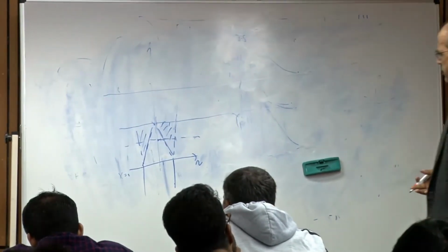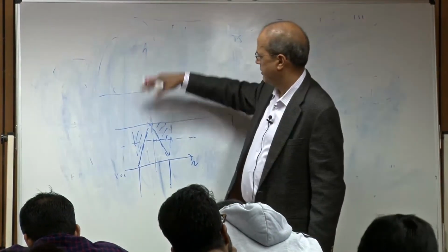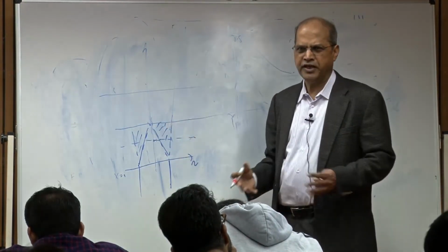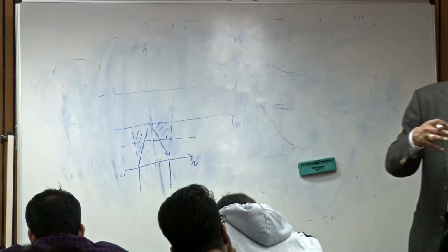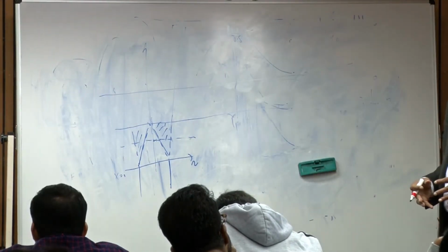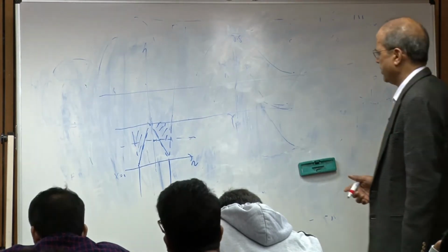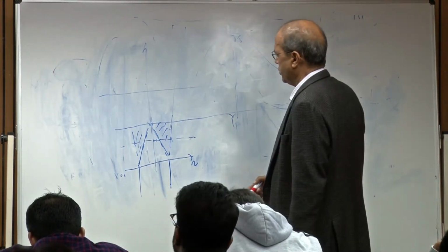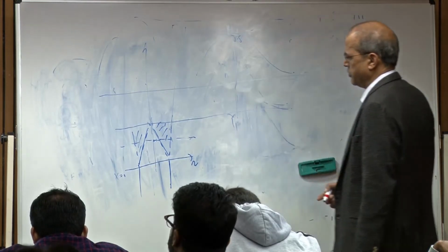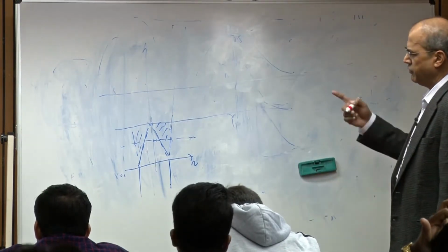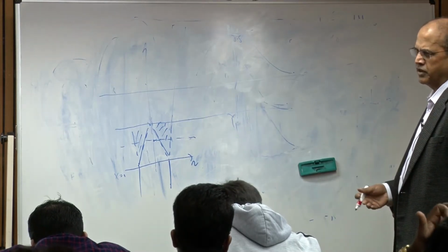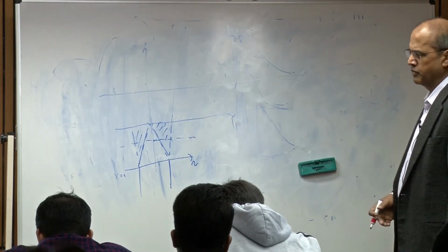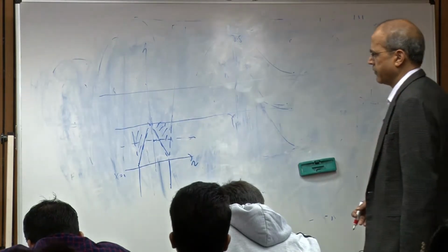So if we can determine the Y_F distribution in a non-reacting jet, we can see where the flame is. We can determine the flame surface. Similar behavior applies to the axial velocity distribution, or if you consider a hot jet, the temperature distribution follows a very similar behavior.